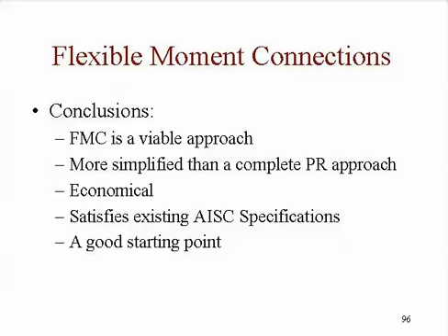Well, this flexible moment connection approach, I think, is a viable approach. It's something that you can do in a simple way. It's certainly a more simplified approach than a complete PR analysis might be. It potentially can give us an economical solution. I believe it satisfies in a general way the AISC specification. Perhaps the most critical part is that I think it's a good starting point. Okay? It gives you a way to maybe understand how these structures behave.